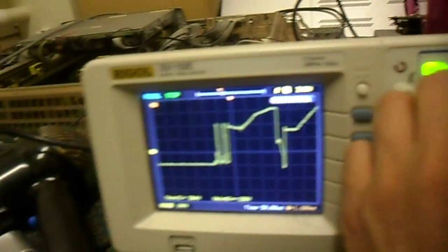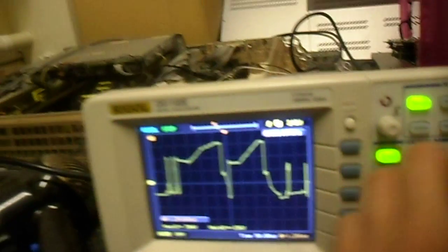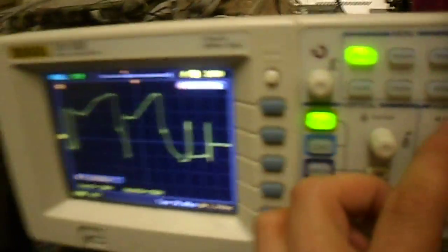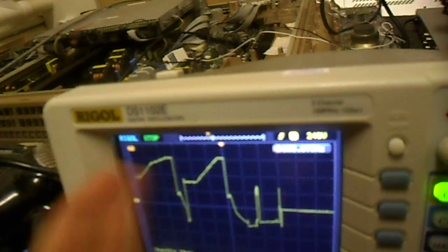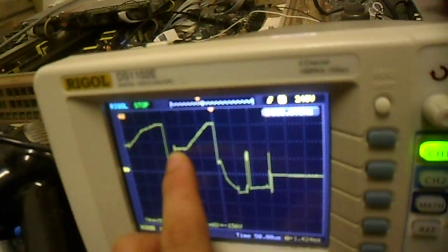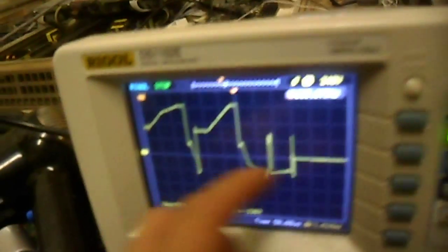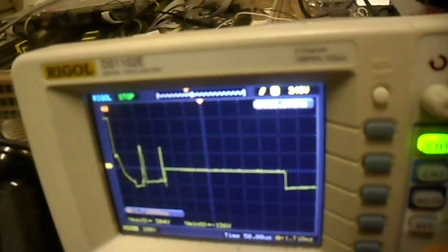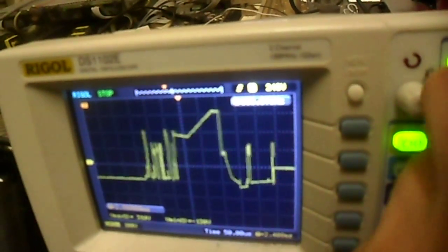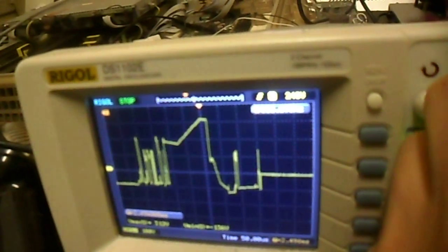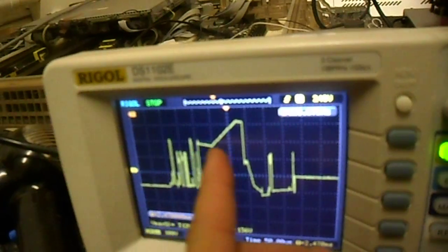I've never seen that before on a plasma display. They do two array periods here, two array and initialization periods here, and another single sustain. So what this probably is, is a least significant bit, because this is kind of like a very weak light emission from the panel. So it gives them extra resolution in the low levels. And then here, yeah, this is obviously some kind of sustaining going on.